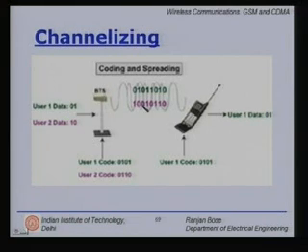So, clearly they are interfering with each other, intentional interference. But at the receiver, if you use the code of user 1 to decode, you dispread your own signal, but spread further the signal received from the interfering user. Thereby, you obtain the useful data for yourself.